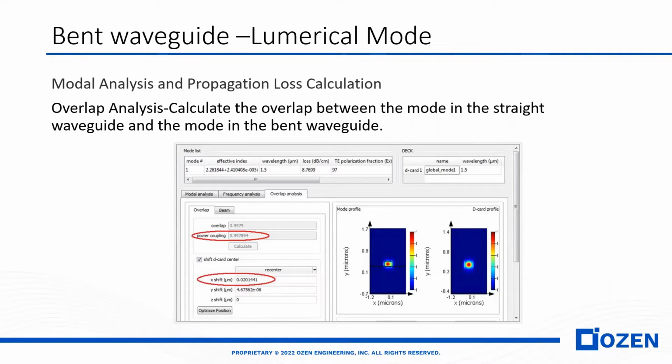We can also analyze the bend waveguide with Lumerical MODE. Actually, in Lumerical MODE, we can do modal analysis and propagation loss calculation. We can do overlap analysis.